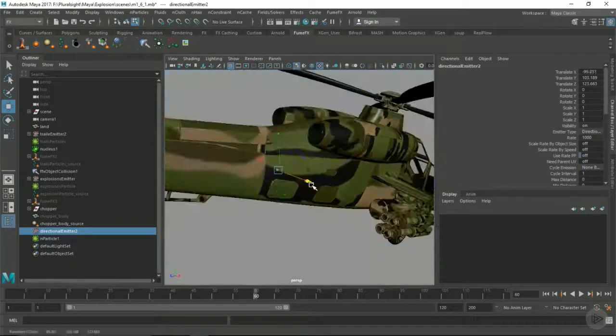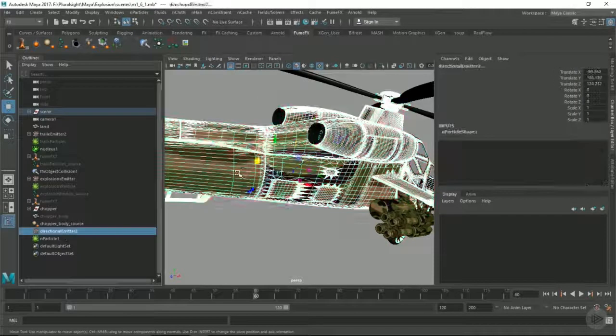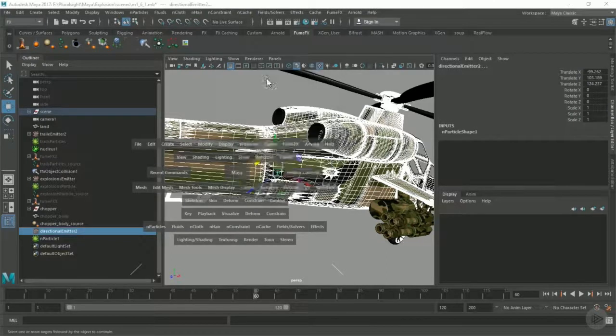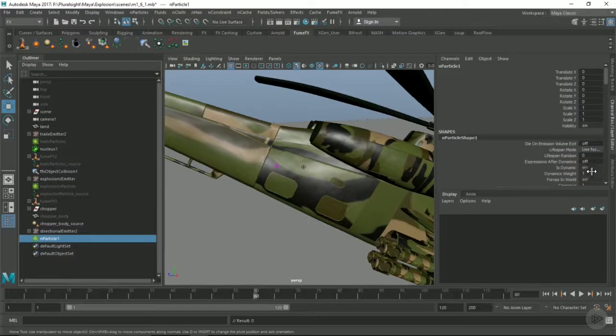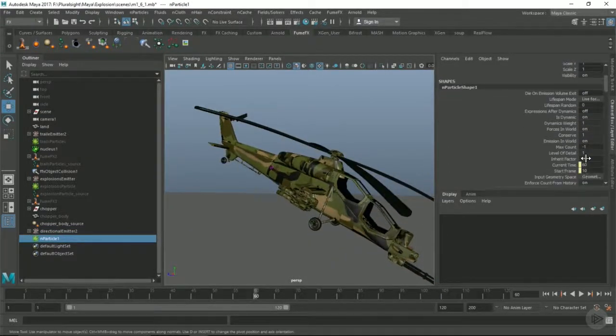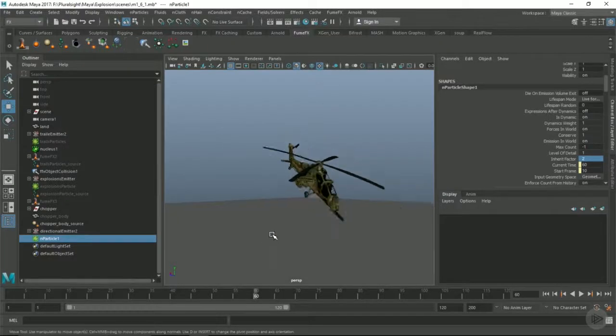And let's constrain that. And now these particles, we're going to have them inherit the velocity of 2. So we're going to make these shoot forward quite a bit. And the idea is we're going to make them a little bit smaller, and we're just going to have them shoot forward to try to push some interesting fluid forward as it passes by, and just give a little bit more of an interesting fluid movement.